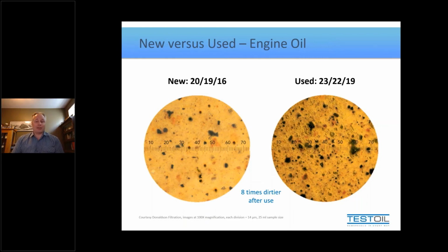Imagine you have a hydraulic system and you ask somebody within your facility to go get you some clean new oil. So if they go out into your lube room and take a look around and say, nah, I don't think any of these drums are that clean. Look at the way they're being stored. So they decide to go to the warehouse. And again, they look around the warehouse and say, I don't like the look of the way the drums are stored here either. So they talk to your warehouse manager and ask what's the freshest oil you have? They want the drum that's been stored the shortest period of time because that is the least likely to build up contaminants in it.